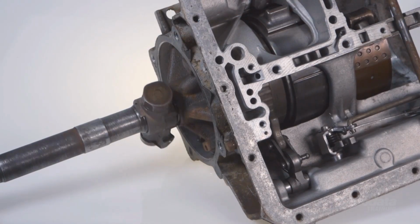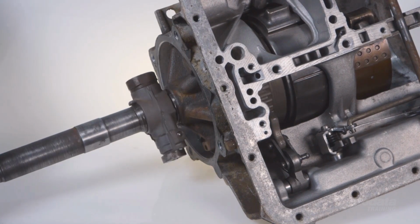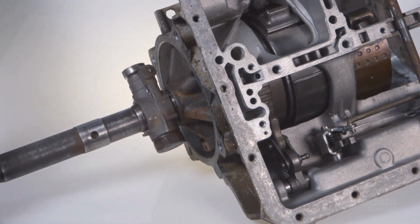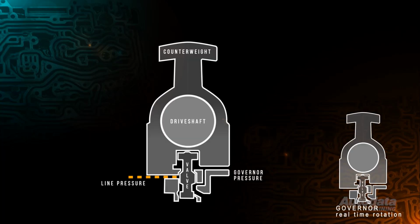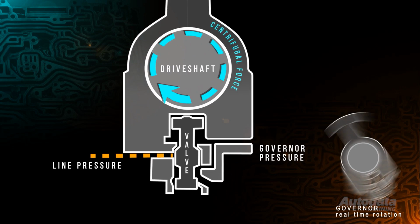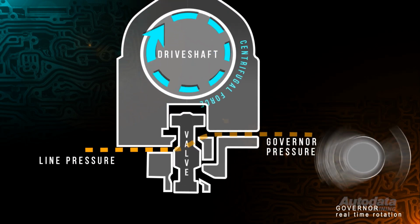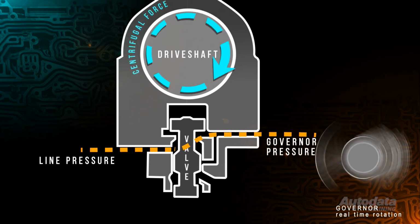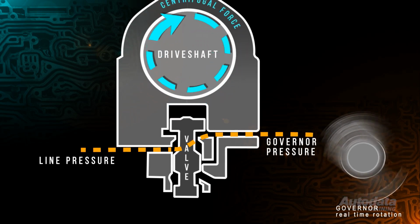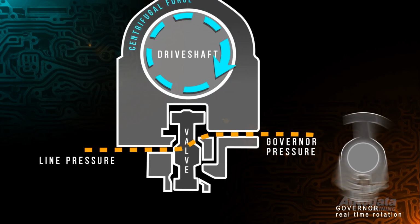The governor valve controls line pressure to regulate upshifts and downshifts in the transmission. The governor valve is located on the output shaft. The governor is a rotating mechanical device fitted with weights that are thrown outward in response to centrifugal force. As transmission output speed increases, the governor pressure will increase. As the shaft speed decreases, the governor pressure will also decrease.